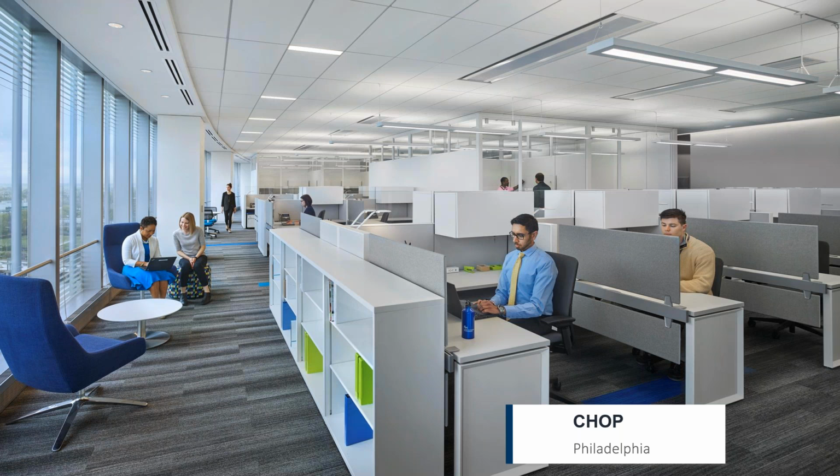In terms of an office space, we want to talk about the Children's Hospital of Philadelphia. This photo is taken from a campus building that we did several years ago, and we're in the middle of supplying their other facility with several beams. What they did here was a two-pipe system in the interior space. So these beams above the workstations are a two-pipe approach for cooling. And then at the perimeter, if you can see my cursor, we've got these dual slot diffusers installed in the hard lid ceiling, and that is an ACBR,